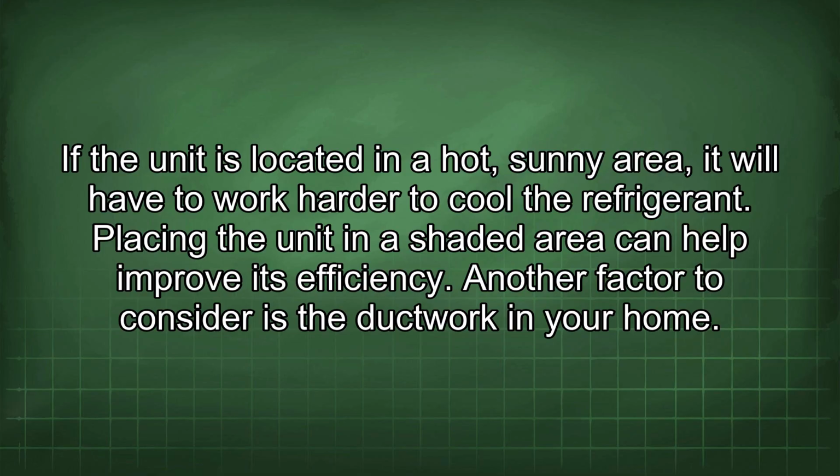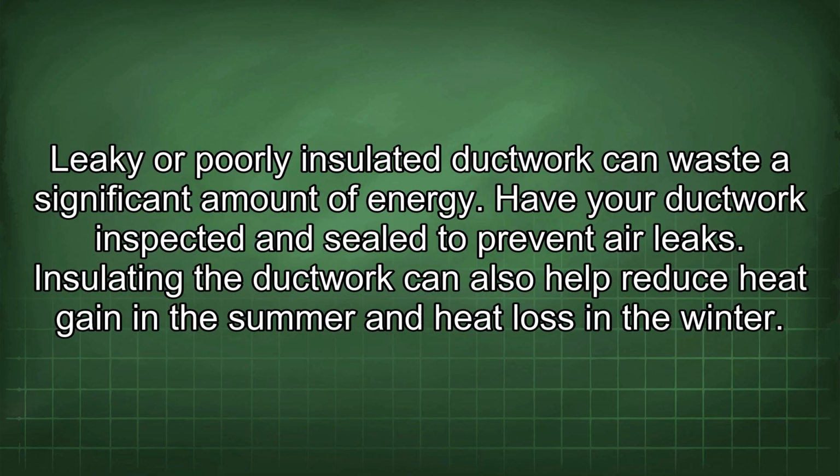Another factor to consider is the ductwork in your home. Leaky or poorly insulated ductwork can waste a significant amount of energy. Have your ductwork inspected and sealed to prevent air leaks. Insulating the ductwork can also help reduce heat gain in the summer and heat loss in the winter.